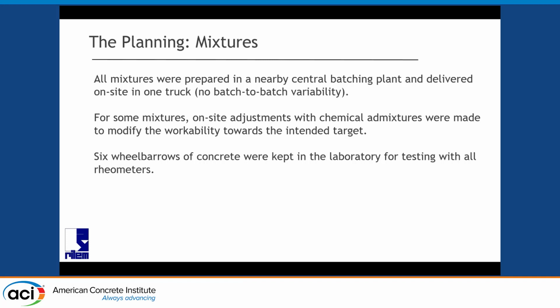Some mixtures we adjusted on the fly, on site, which was a challenge because the company wasn't used to that. Here in the US, it's like, yeah, let's throw in some more admixtures, fine. In France, it was a little more of a trick. We really had to do some convincing to make sure that we were going to do this as well. And then once the concrete was to our desires, with the workability we wanted visually, we did some first tests to see what was going on. We kept 6 barrels and we tested that.